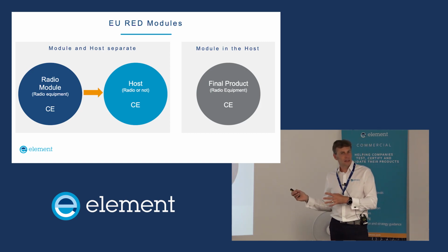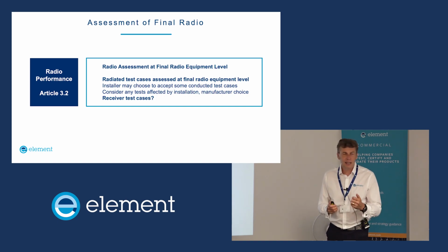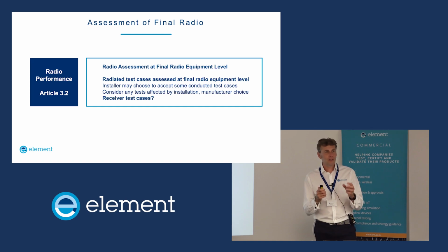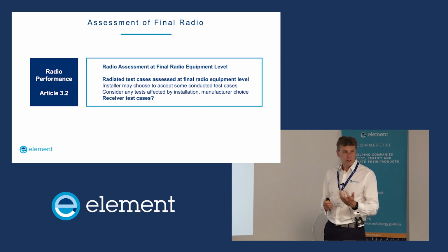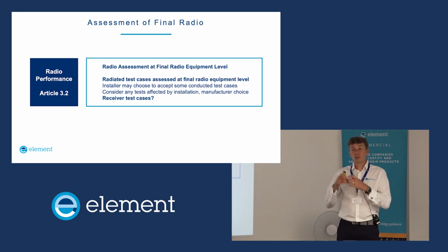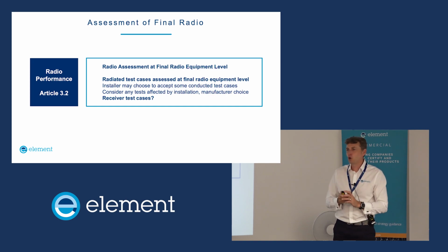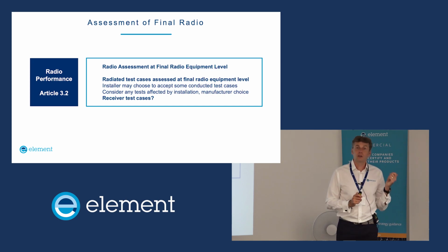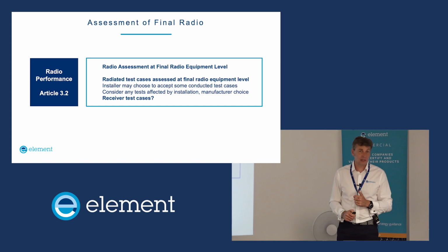But there could be cases where you go, well, as I remember Rob saying, and Rob seems like a pretty clever guy, he said that those transmitter and receiver antenna port tests, they're just conducted out of an antenna port. So I'm going to choose to sort of trust those. And so, in fact, a lot of installers of radio modules repeat full safety testing and full EMC testing, but then for the radio performance, they might say, I'm going to contact the module manufacturer, get their test report for the radio performance, and then I'm going to trust their antenna port measurements, and I'm going to just repeat the radiated spurious emissions test.